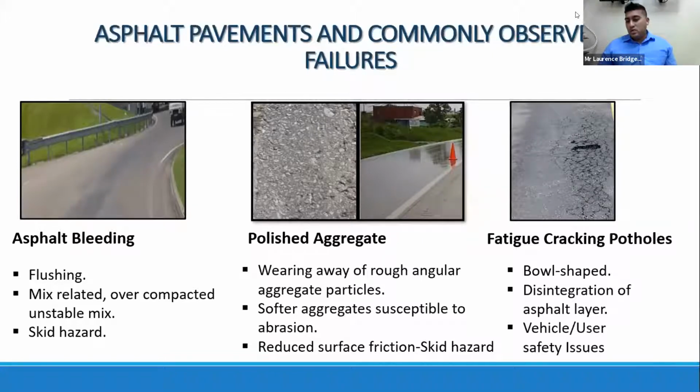Fatigue cracking potholes are another common defect. These are described as bowl-shaped and generate as a result of fatigue cracking or bottom-up cracking that would be reflected to the surface in the pavement. Environmental conditions as well as traction and vehicle movement on this cracked area result in these potholes developing even further. These potholes actually present vehicle and user safety issues for the motoring public.